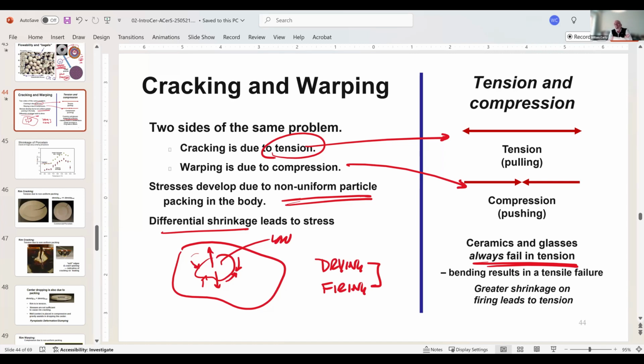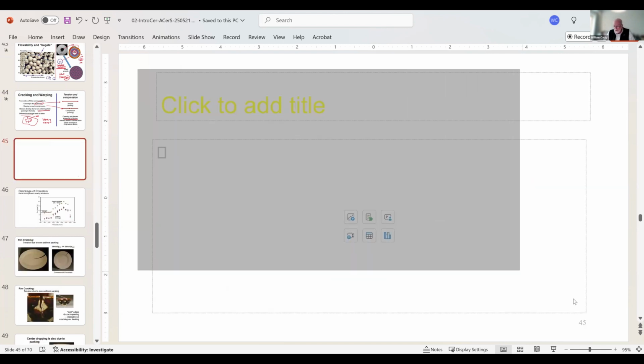Does that mean that I cannot create cracks in drying due to how fast I dry the material? No, but my potential to form cracks in drying is limited, and I've got to work pretty hard to do that. That is due to the fact that I can evaporate water fast enough, because the evaporation of water creates capillary action that pulls the water from the interior to the exterior. So very fast evaporation of water can lead to locking the outside of the system. Similarly with firing.